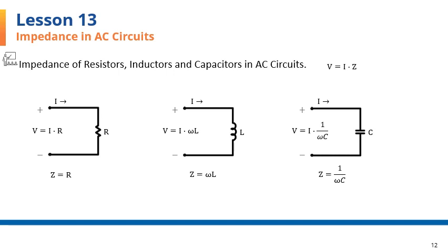To represent the phase shift for the inductor in voltage, we precede the omega L with a j, so the full form of the impedance for the inductor would be Z equals j omega L, because we know that multiplication by j will advance the phase angle by 90 degrees. j, of course, is the square root of negative 1.